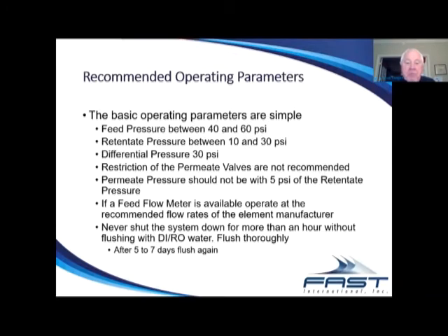If you have a feed flow meter, operate it at the recommended flow rate. And one of the things: never shut the system down for more than an hour without flushing with RO and DI water. I know systems that have been shut down accidentally, power outages, etc. But if that happens, you've got to have a way to flush it. Otherwise, the paint will cause fouling in the system laying static. And if it's longer than 7 to 10 days, flush the system regularly to make sure that you're not having bacteria or bioburden building up in those elements. Next slide.